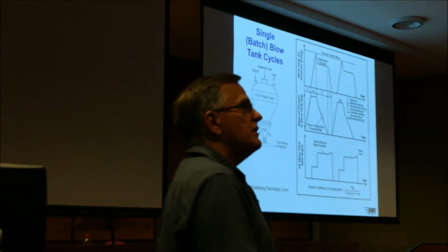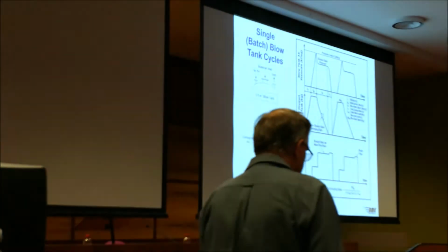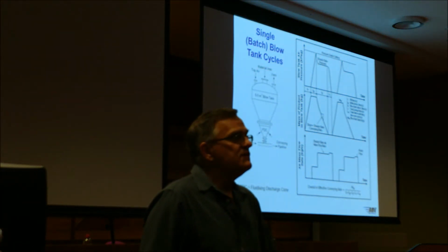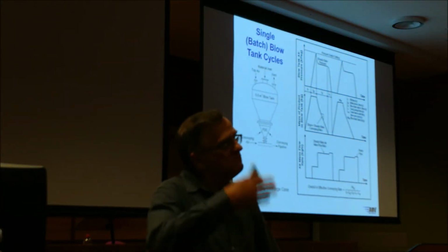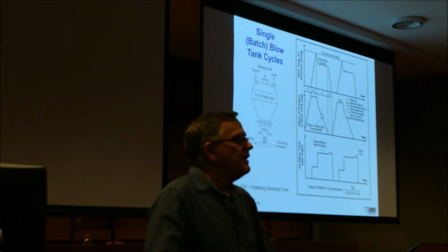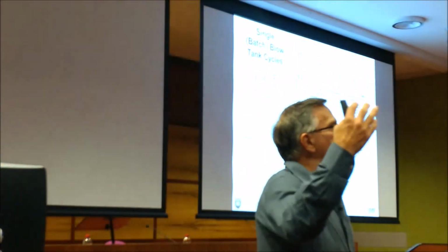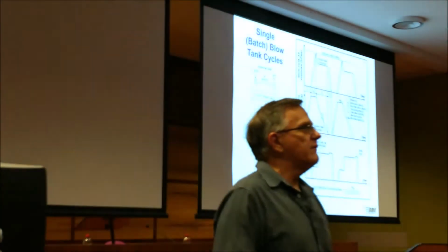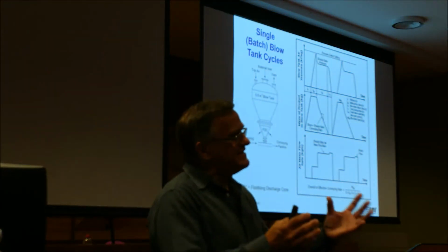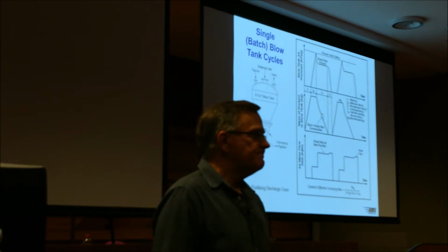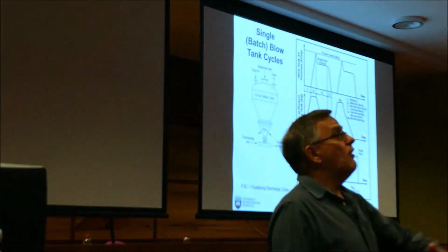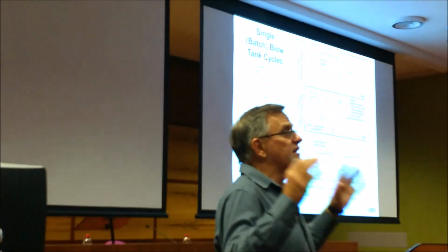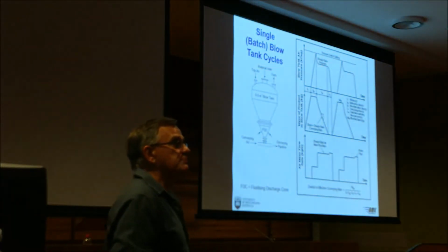So for a single system, a couple of 100 metres, 100 metres, that sort of distance, 10, 20 tonne per hour, no problem. But if you start getting up to hundreds of tonnes per hour, or your distances go up to a kilometre or beyond, a single blow tank is not efficient, because it takes a long time for that product to get there. And if you've got high tonnage, it takes a long time, high pressure drops, etc.